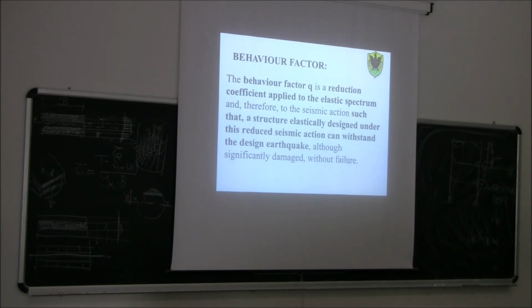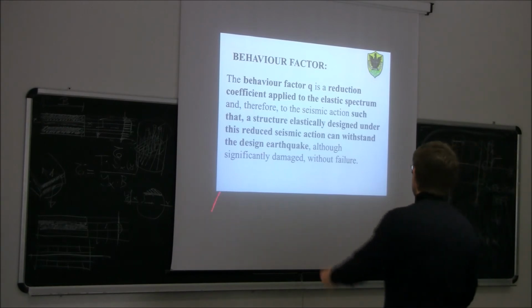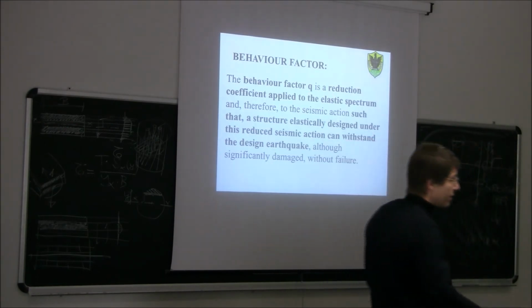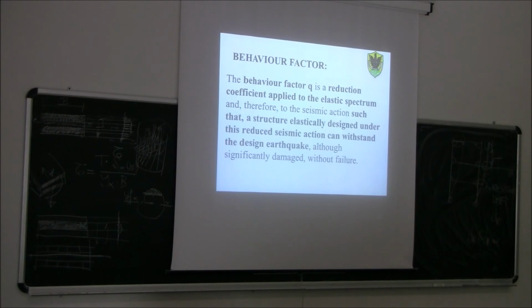Okay. About the behavior factor, what is the behavior factor? The behavior factor is, as you learn in reinforced design, a reduction coefficient applied to the elastic spectrum and therefore to the seismic action, such that a structure elastically designed under this reduced seismic action can withstand the design earthquake, although with significant damage, without failure.